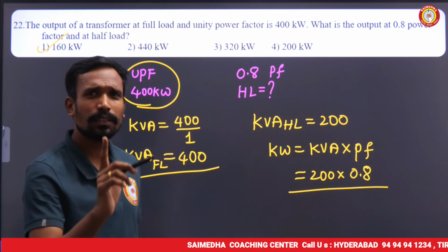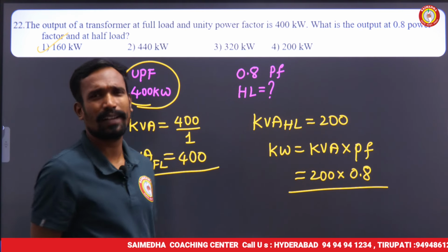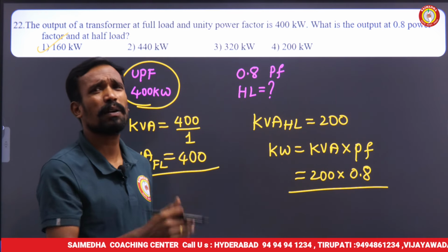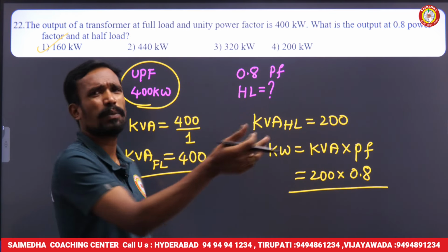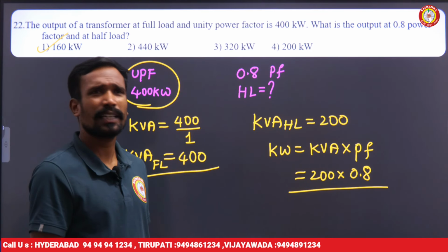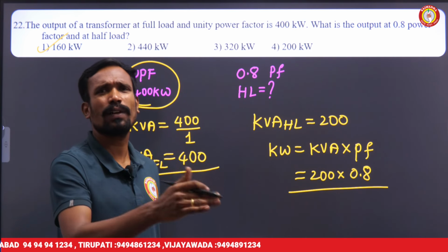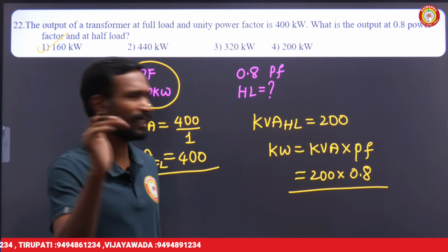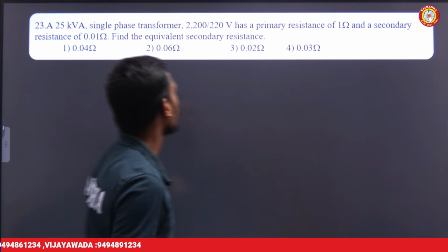So don't judge with respect to kilowatts. If the power factor is not given, then consider unity power factor and try to solve the answer. If the unity power factor is given, of course kVA and kilowatts are both the same. Right, sir? Let's go for the next.